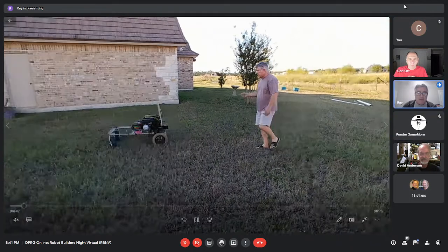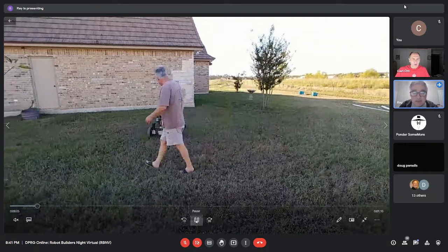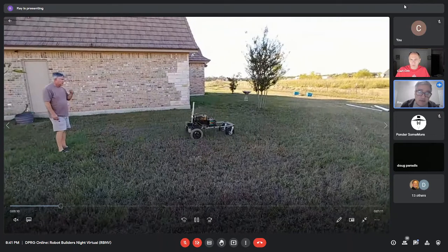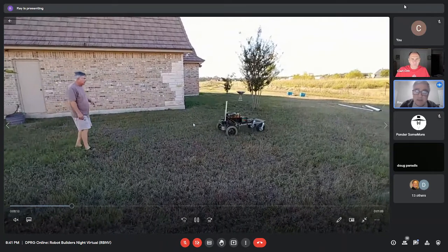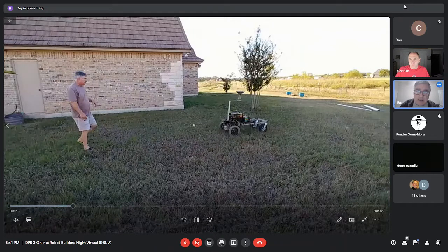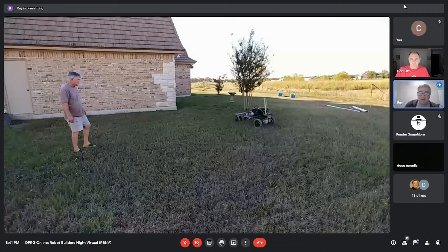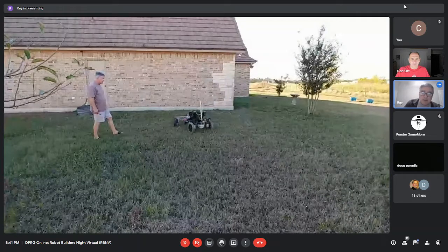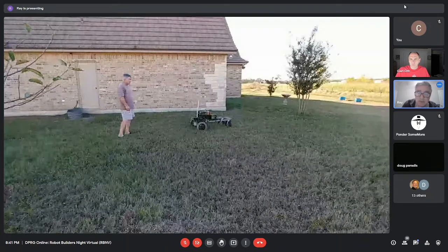Hey, Paul, I don't know if you've ever seen this, but this is a BNO055 on top of I think a two-foot aluminum mast. I'm looking at the yaw angle, or the compass. The robot is basically moving forward about 3 meters, rotating on alternate wheels, and moving back.